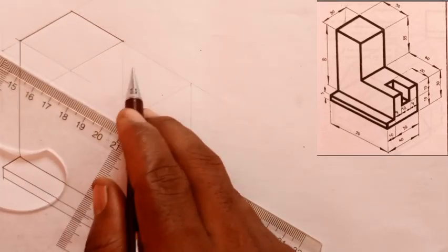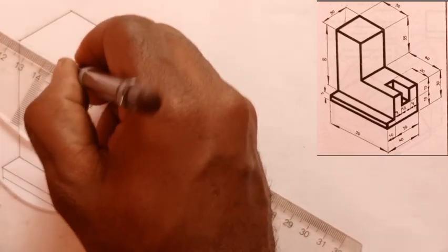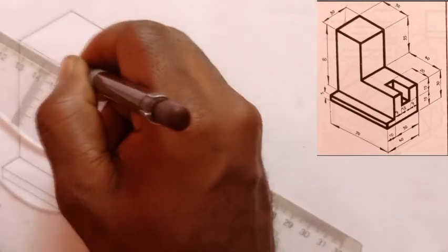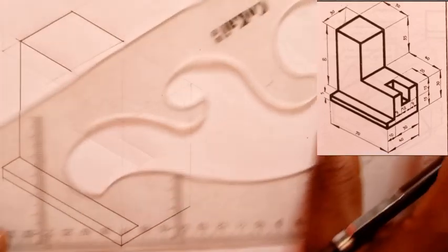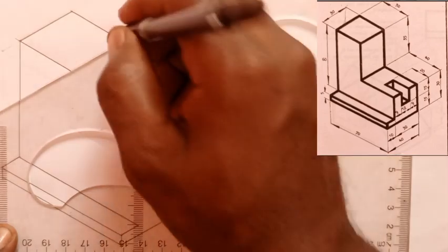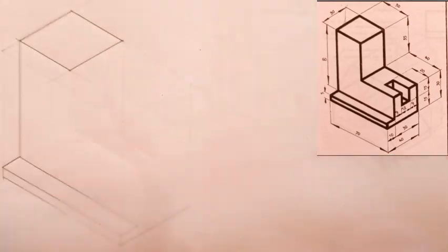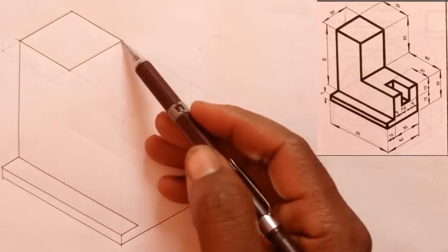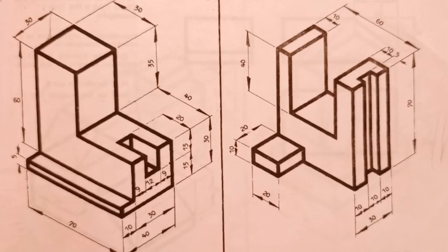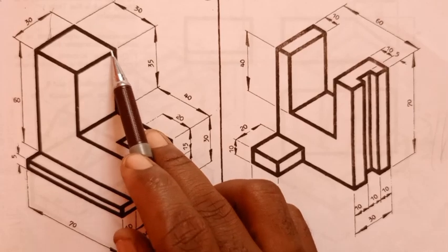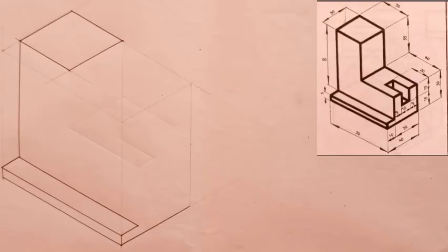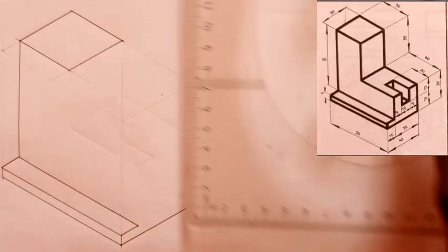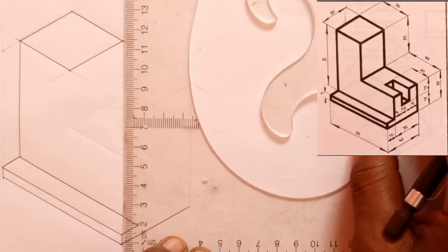So those four corners, I'm going to thicken them. So let me thicken this from here to here. Then from here to here are shown on the top right corner of the screen. You can see that? Now from this point here, which is this point here, I'll measure 35 downward, right? So let's do that. Measuring 35 downward from here, so I'll just show the line from this point downward this way.